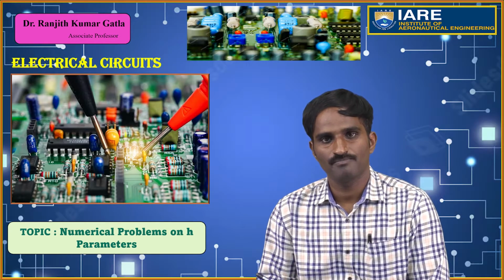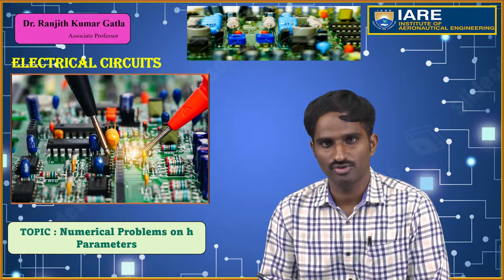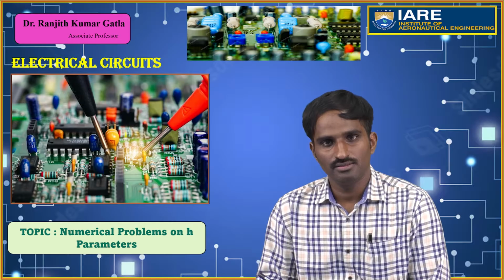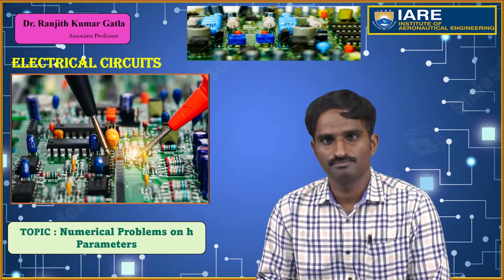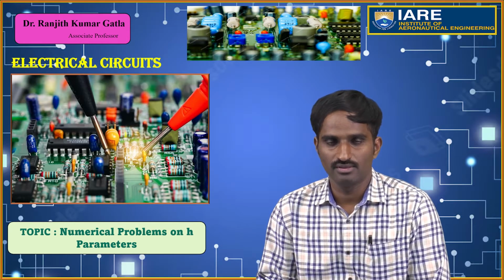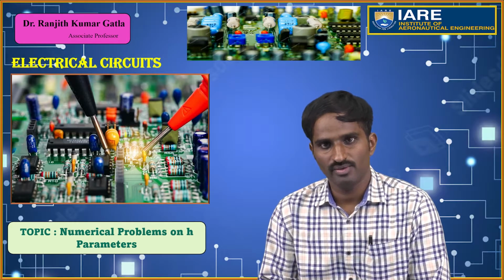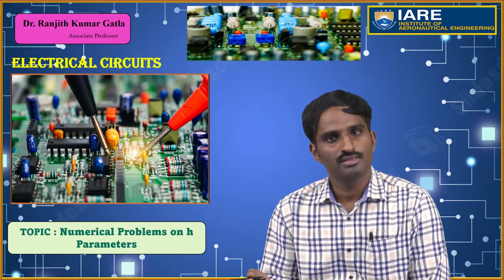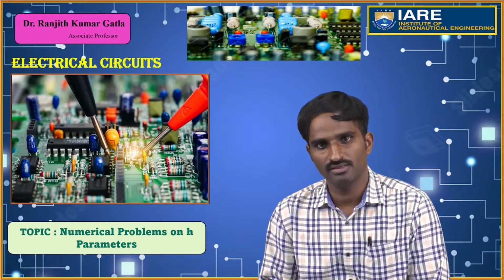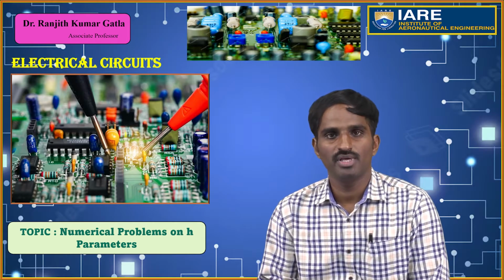Similarly, when coming to the Y parameters, which are admittance parameters, they are also called short circuit parameters. The same way, to find Y21 and Y11, we make the output a short circuit, which means the output voltage is 0, by shorting the output terminals.